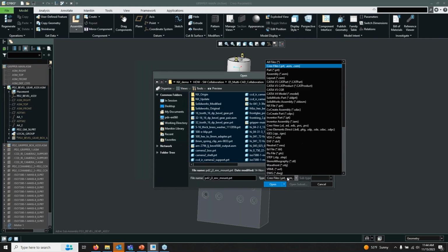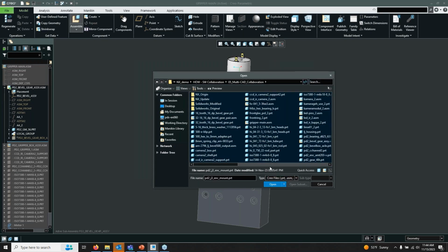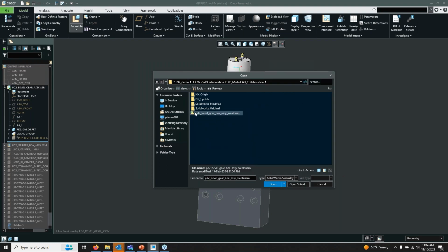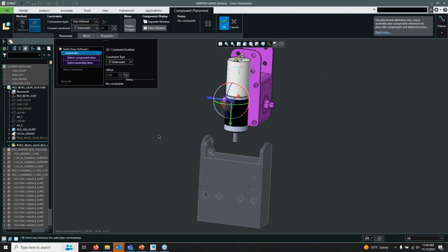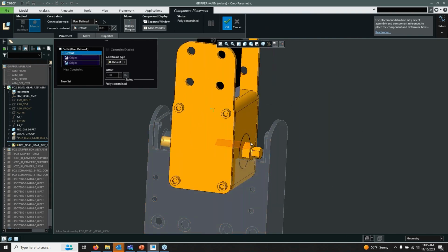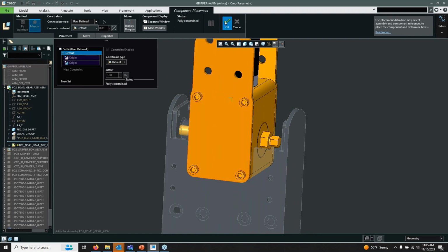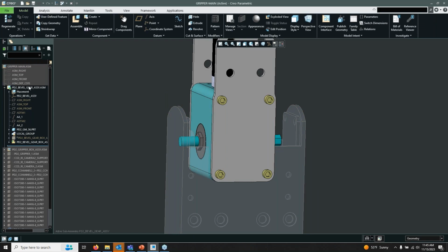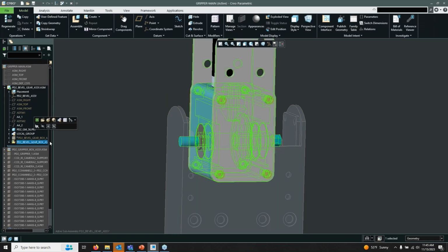Now we'll notice the default file open here showing Creo files. I'm not going to see anything else. Assuming you have this extension, I'm just going to go to SolidWorks assembly. We can see that, down to the symbol used in SolidWorks, we can bring in this file saved as a SLDASM. I'm just going to build this directly into my Creo assembly, and okay. We can see this is integrated flawlessly. Still a SolidWorks file type.